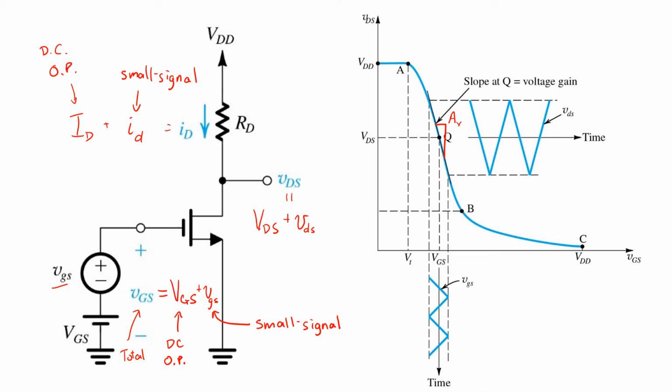As you can see here graphically, there are limits over which this small signal approximation is valid. Obviously, if the applied input vGS is large enough to cause the transistor to enter this region or this region, then the input-output relationship no longer observes this linear relationship, and it's not really serving as a very good amplifier anymore.